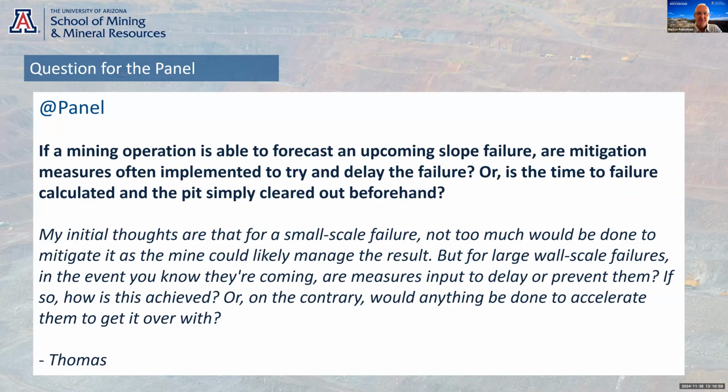So, in terms of the last part of the question, would you try and accelerate it? I think a few of us were chatting the other day about instances where I've certainly had large blocks pushed on a wall that we wanted to move that posed a rock fall threat to a haul road, and we tried to move it by pushing water down the slope to try and release it and to make it move. We were successful in that instance. We've also tried firing projectiles at things, which was a lot of fun, but actually didn't work very well whatsoever. So I'd say it depends, and I'm happy to pass the question over to other panelists.